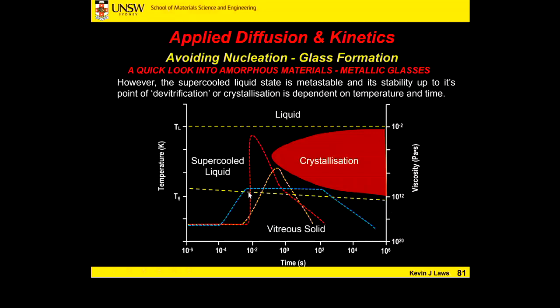When we heat it up again, the structure relaxes once we're above the glass transition temperature. So bonding becomes a little bit further apart. Some bonds no longer occur anymore. So now this material is a supercooled liquid. It now has a viscosity like chewing gum instead of window glass. But because the atoms are now mobile, we've only got, again, a certain amount of time. If we're heating it up, remember our timer is always ticking. We're heating up, time is elapsing. Once we're above Tg, it relaxes.